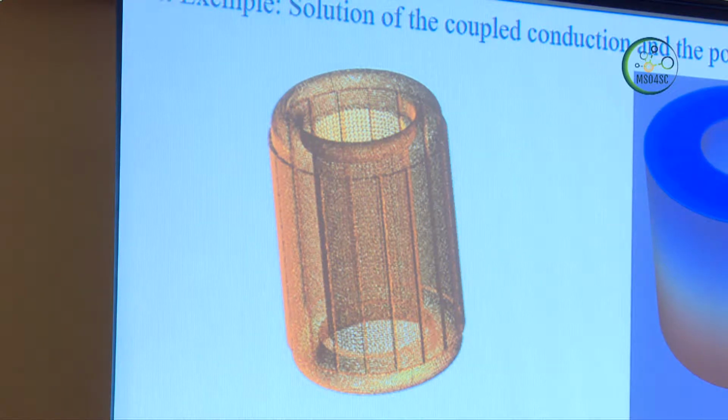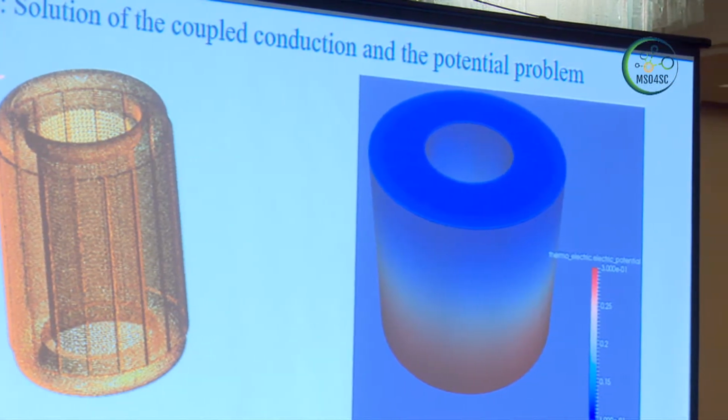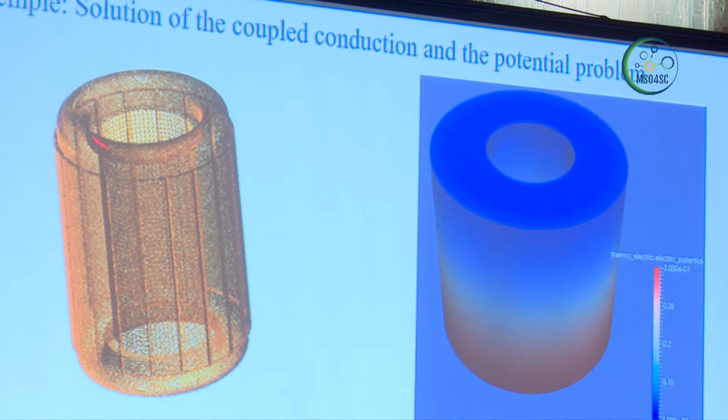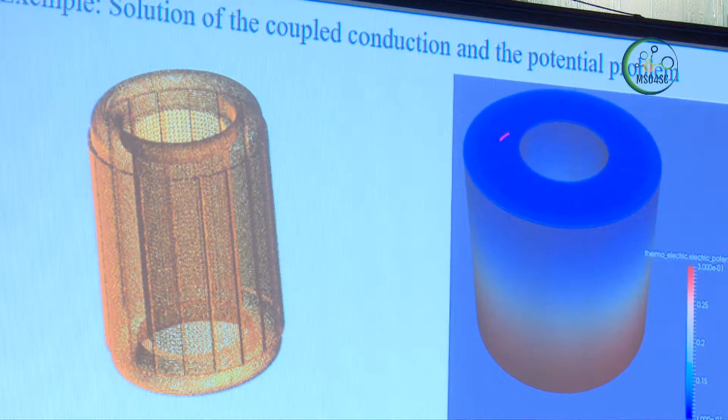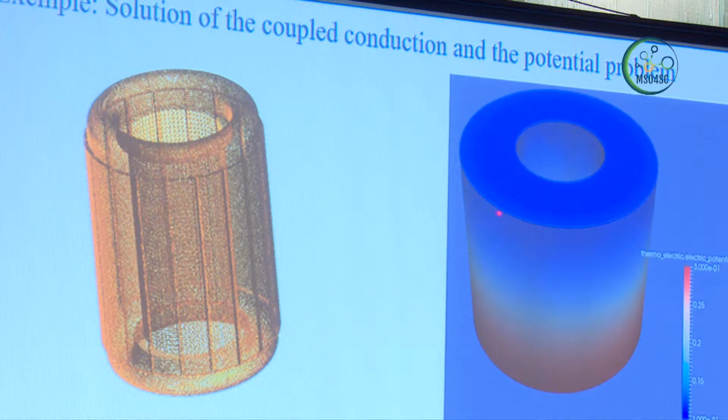I made another geometry where I drop the head of our winding, you can see here, without head, and then I put the potential. Here we have the winding only, here we have the stator, the air gap, the magnet, and here the support of the magnet.